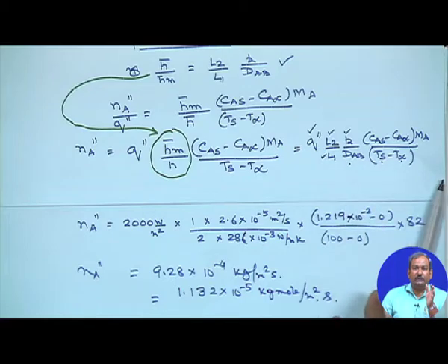So essentially what you see here is the advantage of using the analogy. Since the Prandtl number and Schmidt numbers are equal and Reynolds numbers are also equal, since the length scale and the velocity vary in such a way that length times velocity remains constant, the functional form of dimensionless concentration and dimensionless temperature would be identical.